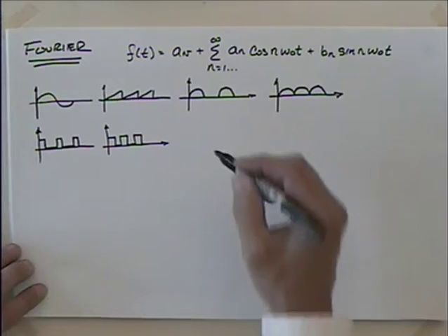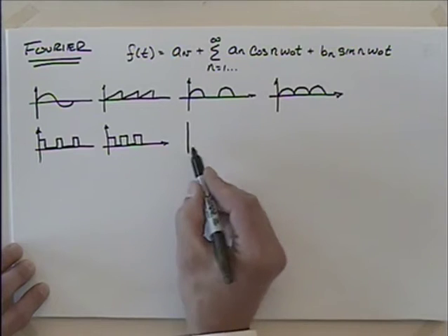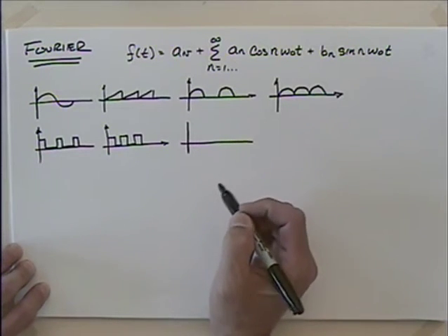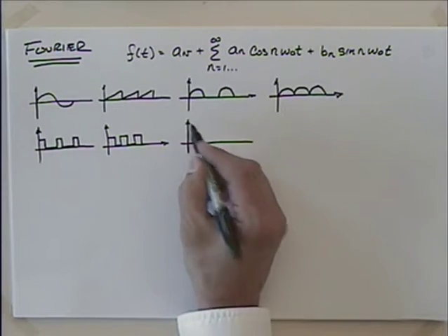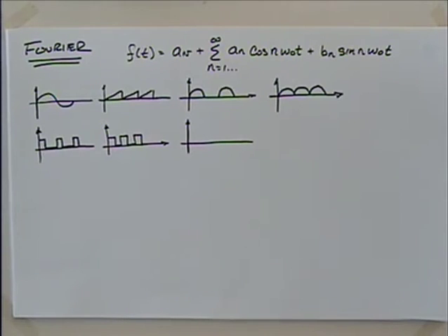If you look at the dimmer in your house, maybe a light dimmer in the living room, you might think you could just drop some of the voltage across a rheostat or potentiometer. That's probably going to set the wall on fire. Because if you have a 100-watt light fixture and you want it to dim 50%, how much power are you going to have to dump in the wall at the switch? 50 watts. Okay, so this is a thought experiment, don't try this at home. Take a 50-watt light bulb and shove it into the wall, all packed with insulation. What's it going to do? Combust? Yeah. So that's why you don't want to do that one.